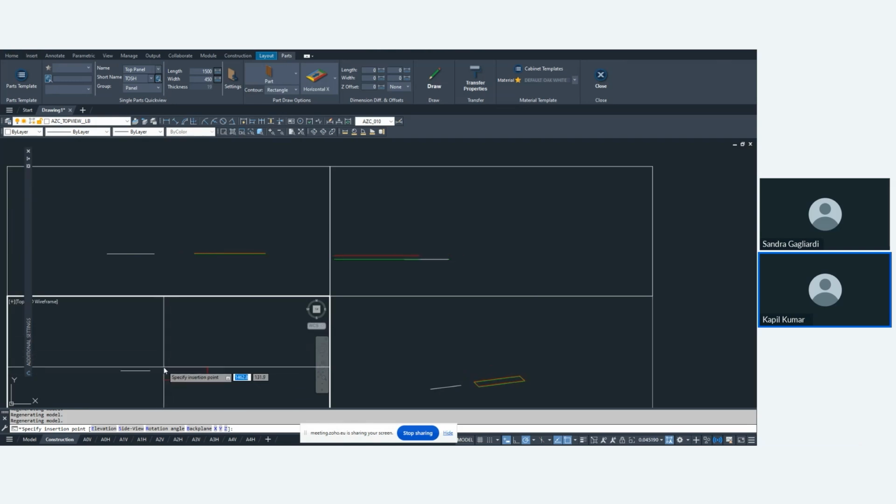But you can see either in front elevation or side elevation, it shows two lines, one is red color and one is green color. The meaning of that color is red is your bottom side and green is your top veneer side. But this is not the accurate position which we have to apply, because our green side should be the upper side. So we go to the option back plane. Now you can check our upper face of the panel is green and the bottom face of the panel is red. So this is our correct position. So we simply drag and drop like that.